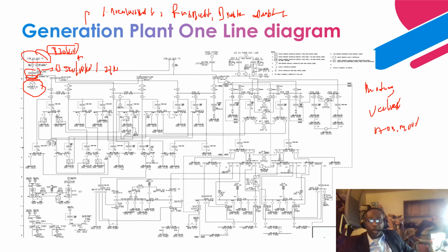Okay, so for motors, you can have a condensate pump motor, right? And what does it do? It basically takes the water from the condenser, right? The steam that basically comes from the low pressure end of the turbine, right? Then once it gets into the condenser, it collapses because it has a high saturation content, right? And also it comes into contact with cold water that is flowing through the walls of the condenser. So basically it collapses and basically forms water condensate, right?